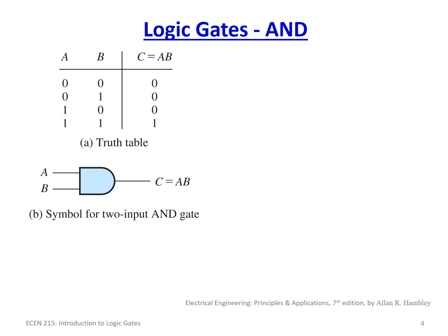And the output function is equal to the Boolean algebra, C is equal to AB. So this has a simple truth table, as you've already seen. The only time that F, or in this case the output C, is a 1 is if A and B are both 1. So that's a 2-input AND gate.